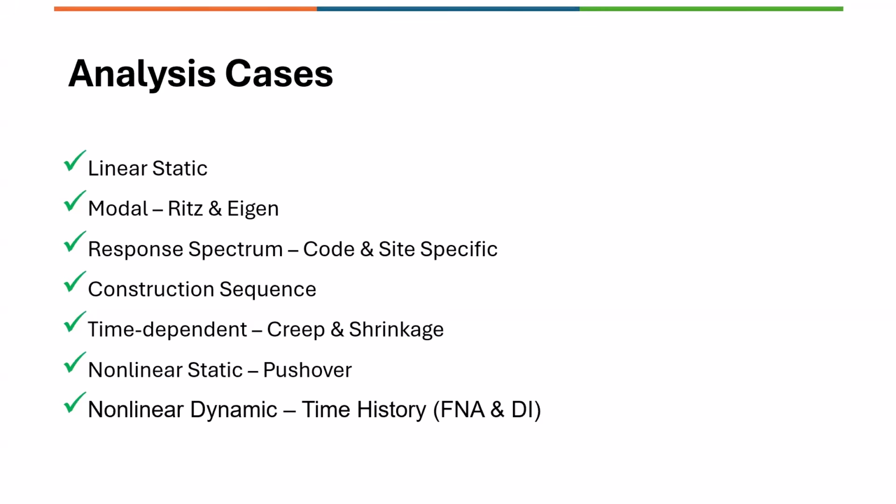For example, the code is talking about the progressive collapse, section 5.8, and key element identification. And for building movements, for gravity columns, etc. So you can utilize the nonlinear static case type for this.